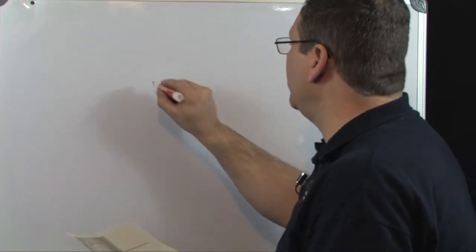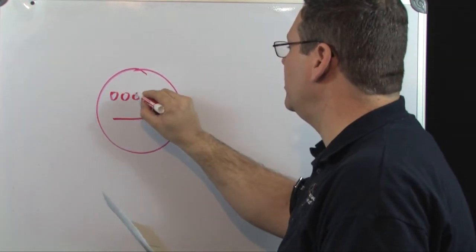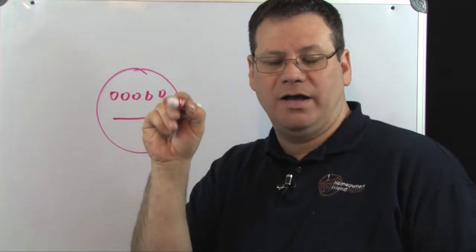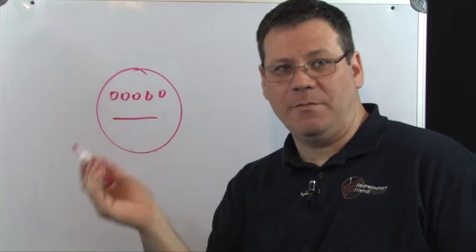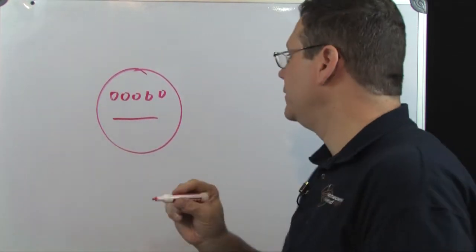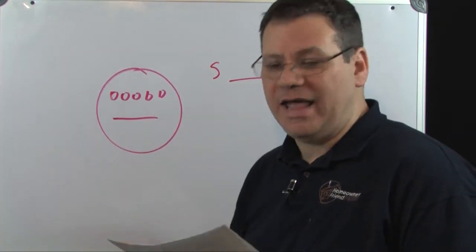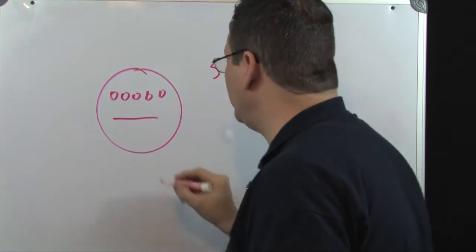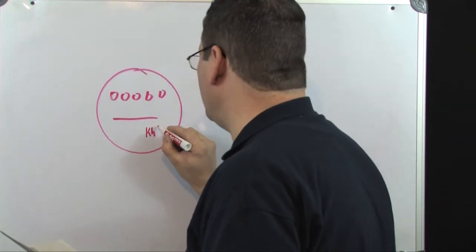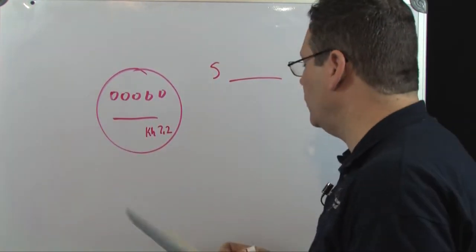And go out to your meter. And of course, your meter is going to have that little spinny disc thing, which you always see, and the numbers are going to be on the top. The spinning disc is going to have a little black mark on it. So you want to first of all find out how many seconds it takes for that disc to go around one turn, and you want to write that down. And the second thing you want to write down is they call the KH number. If you look, there's usually a bunch of numbers on the bottom, and somewhere it'll say KH and then a number. And generally you're going to see 7.2. That seems to be what most residential ones are.